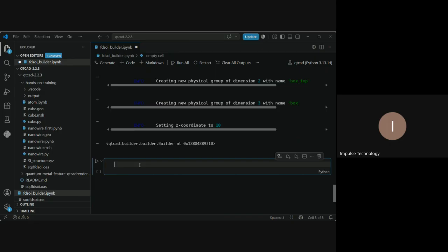And we have to define the silicon thin film layer. You can see in the fully depleted silicon-on-insulator, after the box, we introduce the proper silicon thin film layer. Again, we have to use the bd.use_mask function.